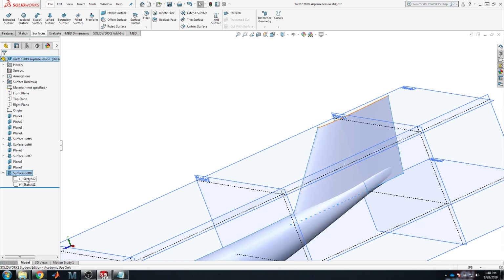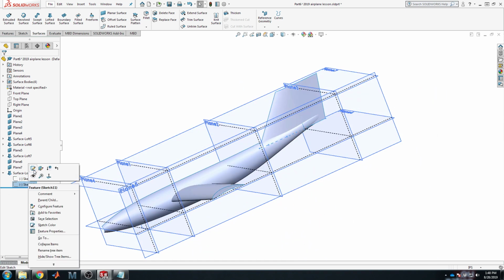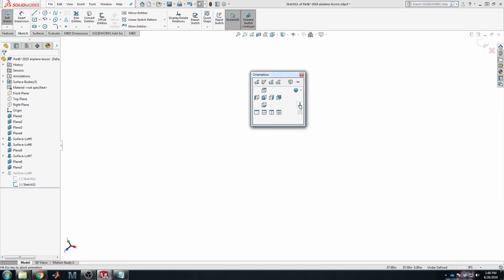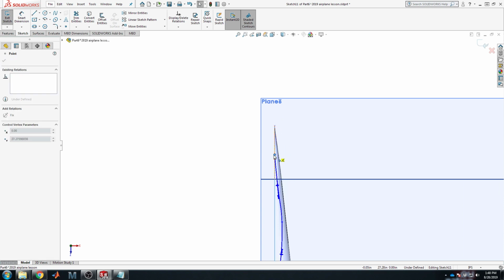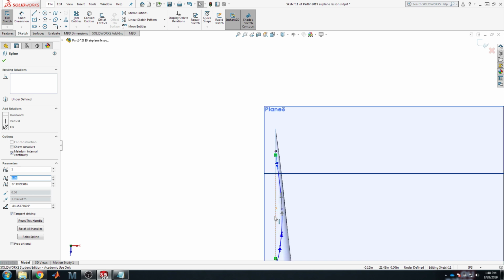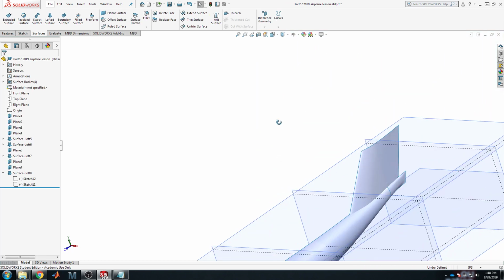You can actually go into this loft, into the first sketch. Which one is that? Which sketch is which? That's the one we want. Right, yeah, 11 is before 12. So we'll edit that and pull the trailing edge a bit forward just to make this work out and stay inside the airplane. Oh, it has control points. Delete. Snap to the center line. Reduce that stiffness a bit just to make the shape nice. Does it look decent? That might be okay. So it's all inside the OML now?